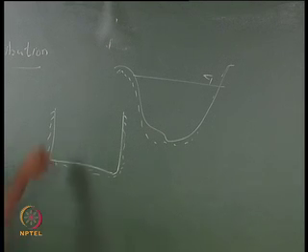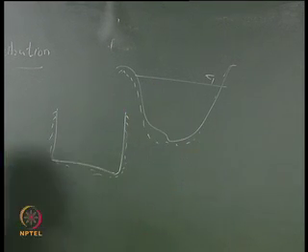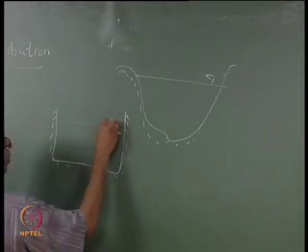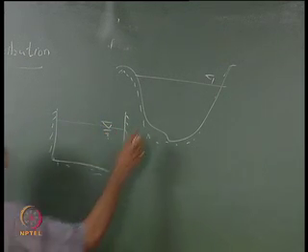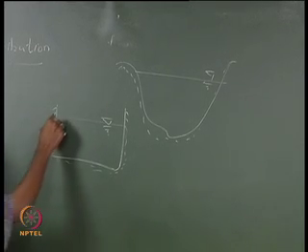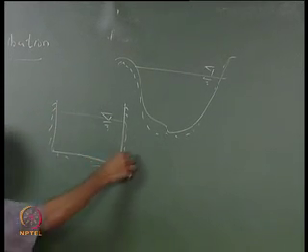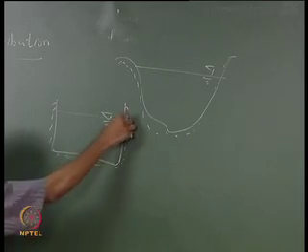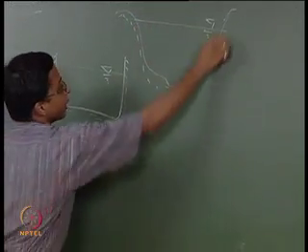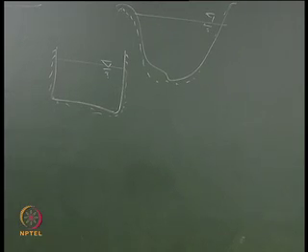The velocity varies at any cross section. It has been suggested to you. How does the velocity vary? We suggested that there will be shear stresses along the boundaries, on the side boundaries as well as the bottom boundary. Similarly, in natural drains also there will be shear stresses.